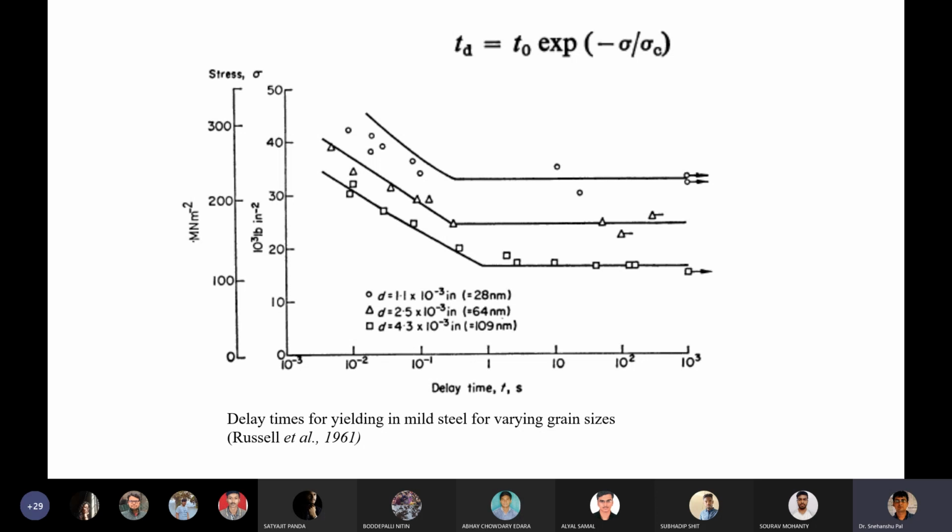stress required to be more. So yield stress is increasing, but the delay in fracture is not so high. Delayed fracture is seen for the higher grain size, but the yield strength will be lower. This is a very important thing. When you reach that yield stress point, if you want a stronger material, then maybe you go for finer grain size, but you may have a problem that it actually reduces the delay of the fracture occurrence.